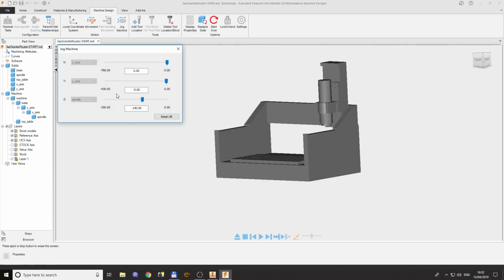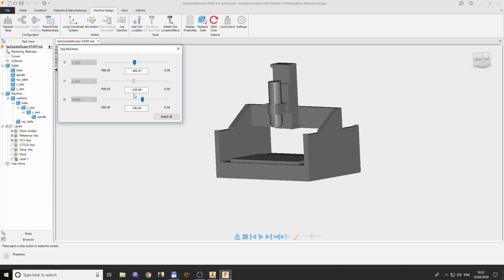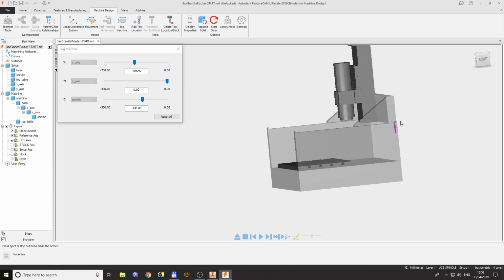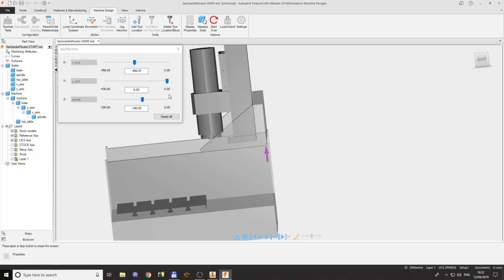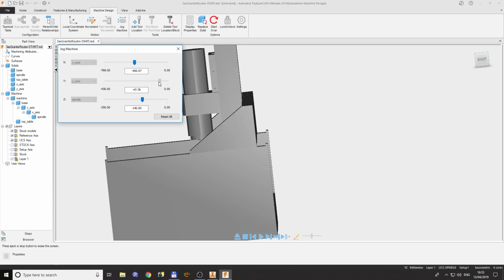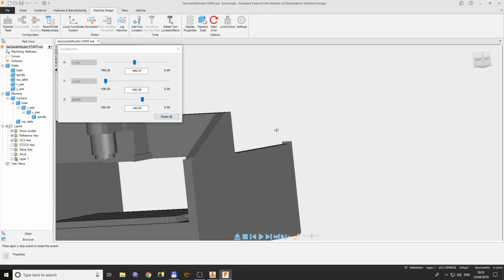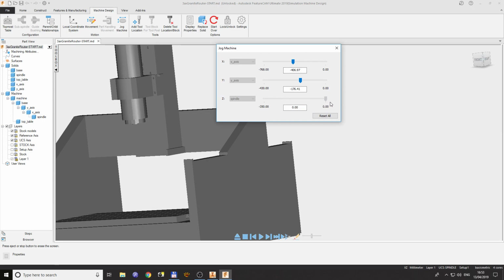When you go to jog machine, so we test x-axis moves just fine, but when we go to y-axis, then this is what happens. Goes there, that is okay, go back, bomb, it hits this bumper, and that basically collides there. Now you have to play with the numbers again, and then find the right setting for your design, but you can avoid this. That is exactly what's missing there. Let's move this back and move it down and up.